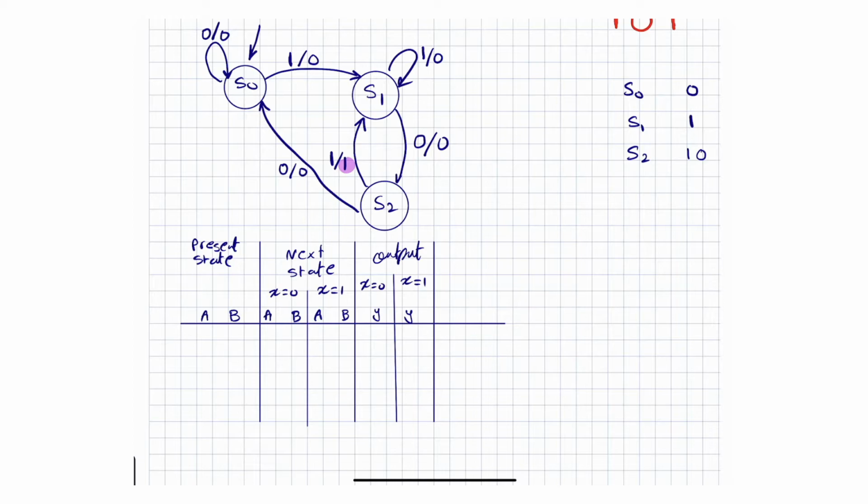Okay, so the next step in the design procedure is actually figuring out the state table. So if I've decided to code it with binary, all I have to do is just figure out that I need a couple of flip-flops. I'm going to call one A and the other one is B. And of course, because I have Mealy outputs and I have 1 input, I'm going to say X equals 0 and X equals 1 in here for the next state. And of course, because I have a Mealy output, the Mealy depends on the value of X. So I'm going to do this in here. And of course, all I have to do is just say 0, 0. That's the first state. And then I have the second state, or is S1. And then I have S2 in here. Technically, I don't need S3, but I'm just going to write it for the sake of completion.